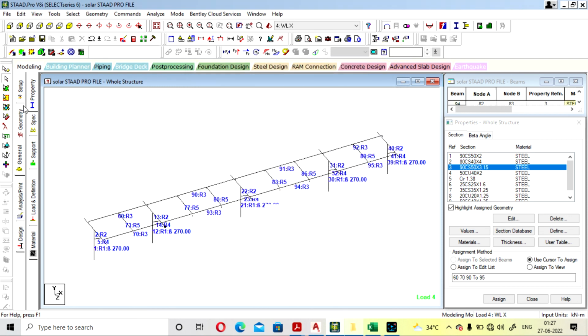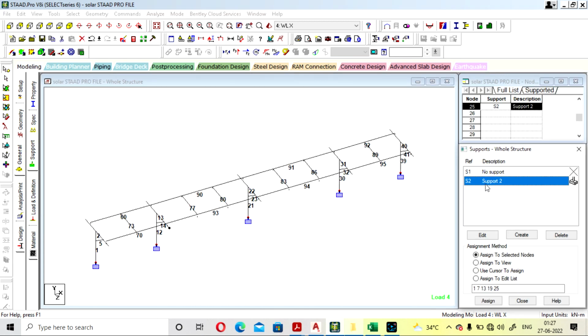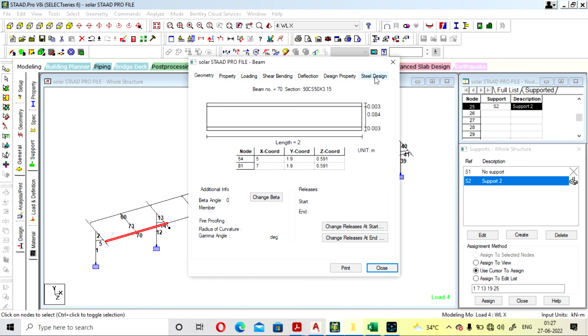And if you haven't seen this, we have also provided the supports from here. So this will be your support. Okay, all the supports will be provided, and we have done the structure here, and just changed the purlin size, as the load taken was not going to be survived by the purlin, so you have to increase the size of the purlin here.